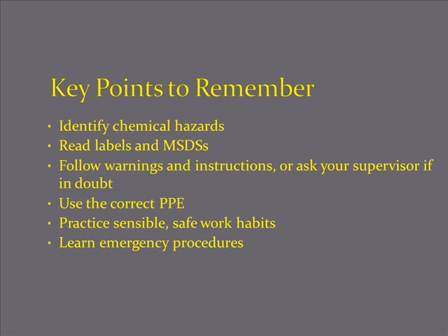Key points to remember when referring to MSDSs or hazard communication. Identify chemical hazards. Read the labels in MSDSs. Follow warnings and instructions or ask your supervisor if you're in doubt. Use the correct PPE. Practice sensible, safe work habits, and learn emergency procedures.